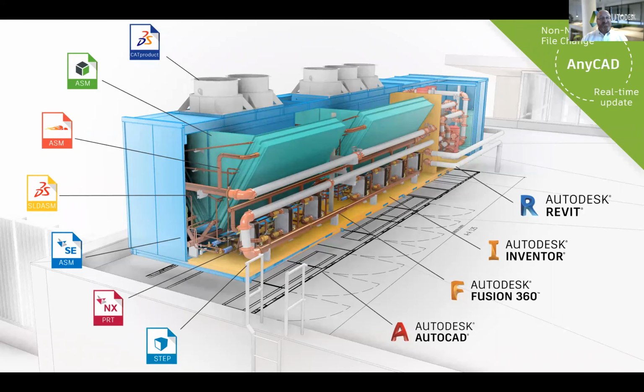The technology behind this is known as AnyCAD, and it allows us to reference CAD files into Inventor from other CAD systems without file translation. And so this is huge. You're able to take any of these CAD file formats, bring them directly into Inventor, and continue to develop your manufacturing drawings, your bill of materials, all of the information that you need to produce in the end.